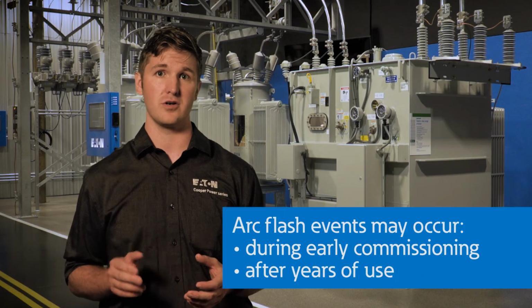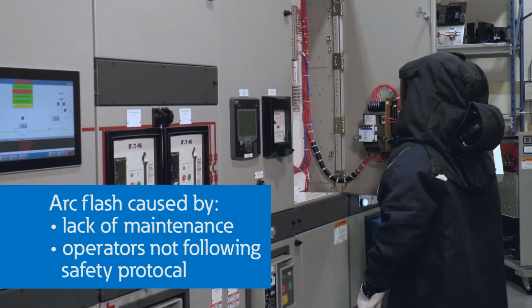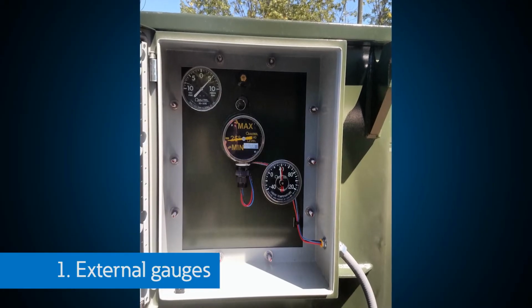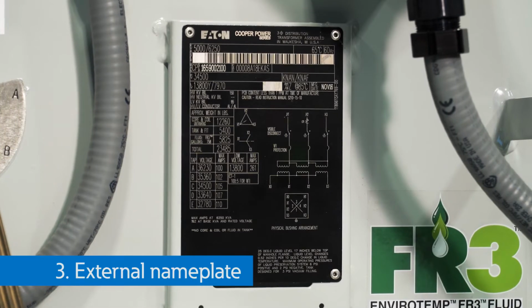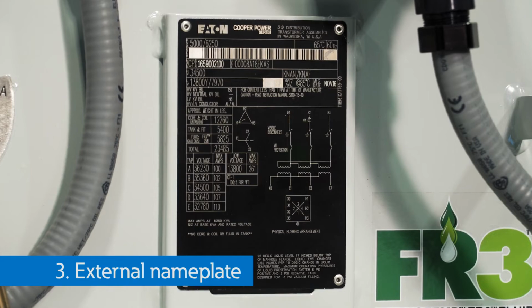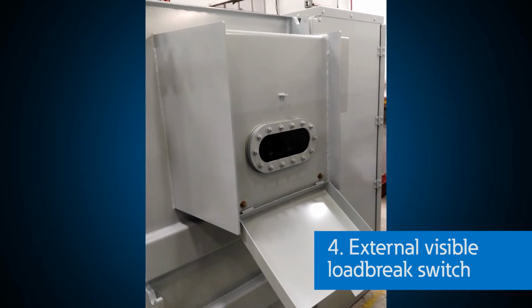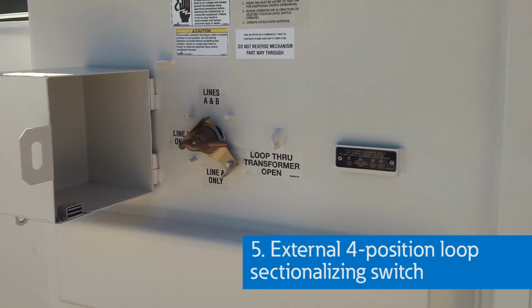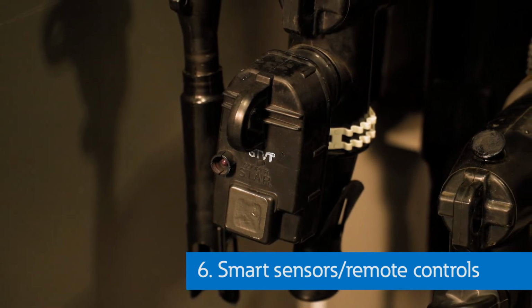Arc flash events may occur during early commissioning or after years of use, but are often due to lack of maintenance or operators not following safety protocol. Risk reduction involves reducing the likelihood of an arc flash event occurring. This would include incorporating features like, number 1, gauges mounted on the outside of the transformer, 2, external fluid sampling ports, 3, externally mounted nameplates that you can see without opening the enclosure, 4, externally accessible on-off or load break switch to ensure the transformer is de-energized before access, 5, a 4-position loop switch mounted externally for sectionalizing control, or 6, even adding smart sensors and controls so you can remotely monitor your transformer.